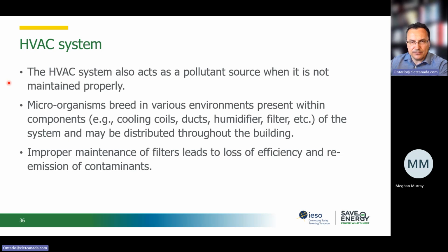We hear, I wouldn't say frequently, but once in a while we hear about cracked heat exchangers in rooftop units that release flue gas into the space and poison the building occupants with combustion products. The worst case scenario here would be an incomplete combustion that releases carbon monoxide into the space, into a conditioned space.